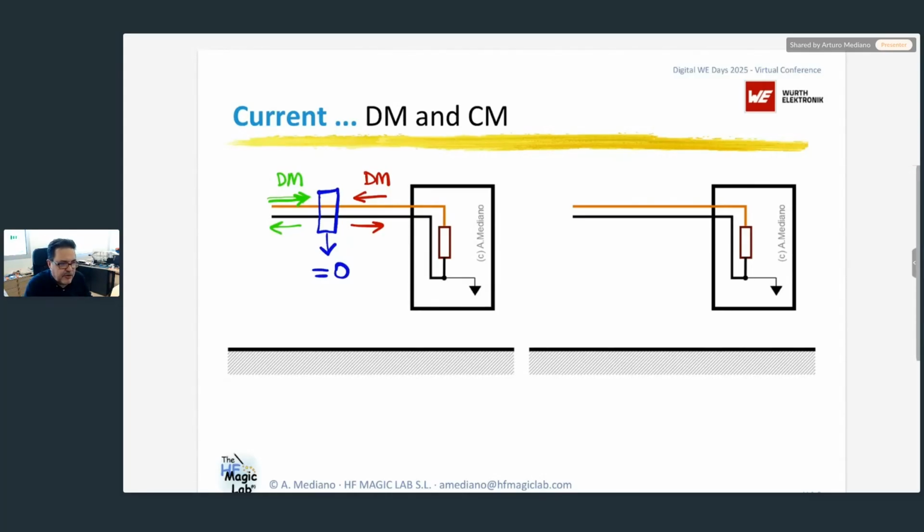We talk about these differential mode currents, and usually for EMI this is not dangerous, because you need many milliamps of current and a big loop to be able to radiate to the environment. Usually the two wires are close to each other, so the loop is small. Obviously, if you have a big loop or a high current, you can create differential mode radiation, but this is not as common as the next situation. In the next situation, we put a current probe, and the output of this measurement is not 0. How could we represent this non-zero situation? Usually, we talk about common mode current.